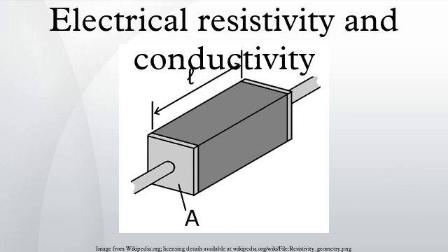In extrinsic semiconductors, dopant atoms increase the majority charge carrier concentration by donating electrons to the conduction band or accepting holes in the valence band. For both types of donor or acceptor atoms, increasing the dopant density leads to a reduction in the resistance, hence highly doped semiconductors behave metallically. At very high temperatures, the contribution of thermally generated carriers will dominate over the contribution from dopant atoms and the resistance will decrease exponentially with temperature.